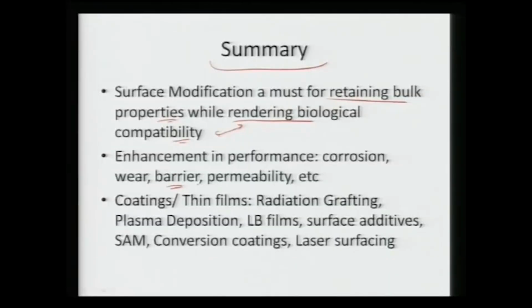It can be in terms of wear, corrosion. We can impart coatings of diamond, we can impart certain barrier coatings to improve the wear and corrosion resistance. We can also induce certain barrier performance. We can have some barrier layers. We can enhance the blood compatibility. We can also increase the permeability, such as in hemodialysis. We want the oxygen to go through, but again the surface has to remain corrosion resistant. So, we can impart certain functionality or improve the performance by incorporating the surface coating, thin films and grafting.